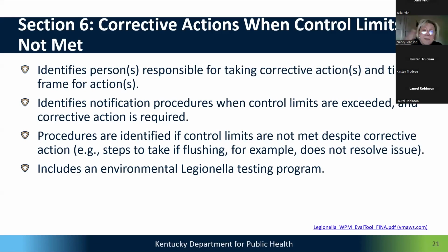This all has to be down on paper and something that's thought through, including your environmental Legionella testing program. We have seen situations where a facility will have a problem with Legionella exposure and they have not thought this through. They have a testing agency that just keeps coming up with, it's negative this week, and then wait 2 weeks, it's positive again.